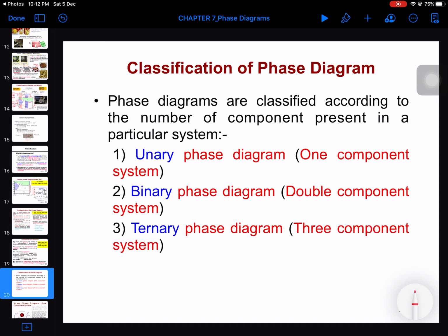The addition of an alloying element represents another degree of freedom, which allows two distinct forms or phases to coexist under equilibrium conditions. The heterogeneous equilibrium phases in binary alloys can occur in solids, or when liquid and solid phases change during melting or solidification. So it's a two component system.